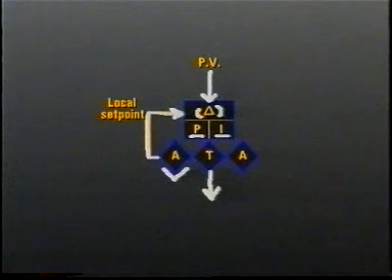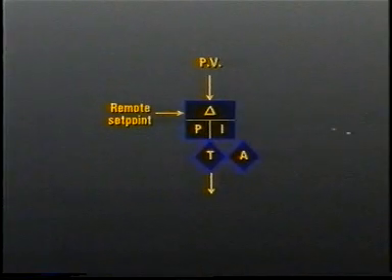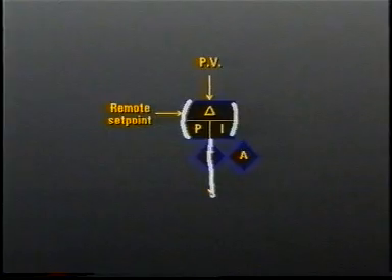It should be noted that the fact that adjacent diamond symbols are touching does not necessarily mean that they are functionally linked. Now let's examine our second illustration, which is for a remote set point. As you can see, this configuration accomplishes the same signal comparison and processing, but this time the new set point signal can only be forwarded automatically. The manual option has been removed.